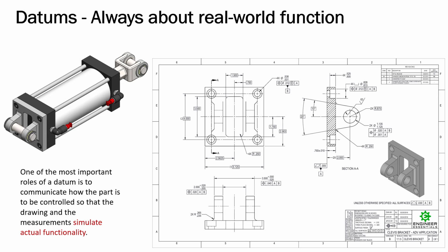This takes a lot of the ambiguity out of this, because if we sent this out to 3 different vendors and they're looking at this drawing, there will only be one interpretation to it. These feature control frames with the datum reference frames within them, it's put in there so that every single person interpreting the print will interpret the same way. And they understand that it will be locked down first on A and then on B.